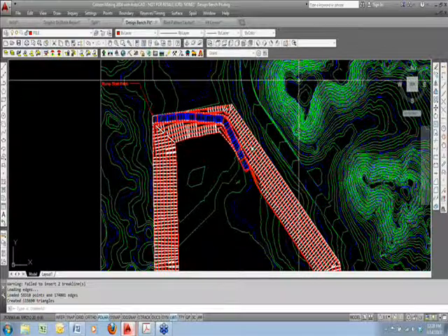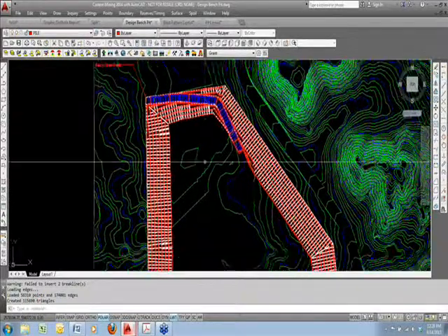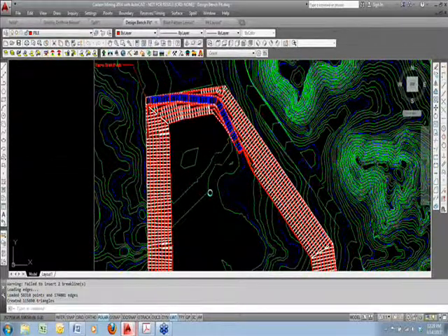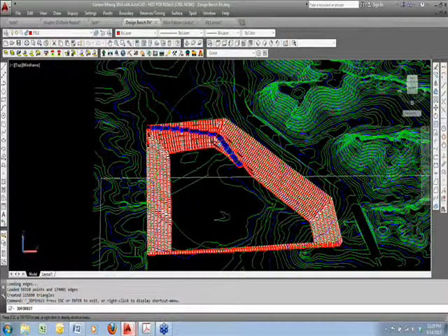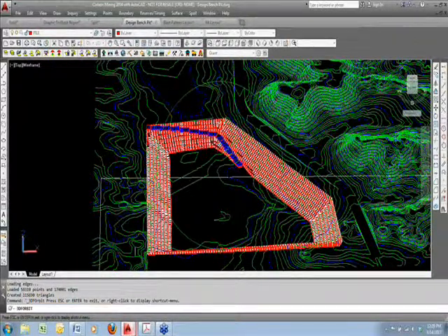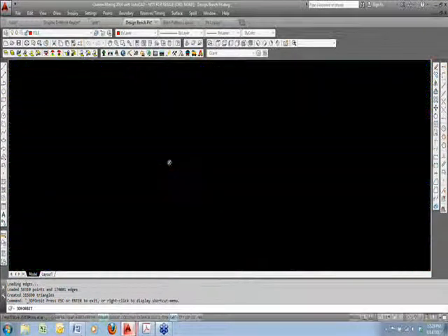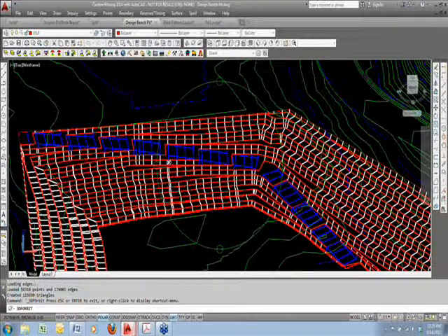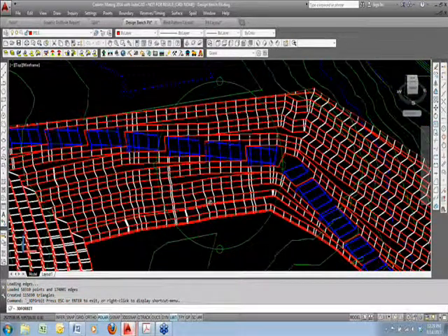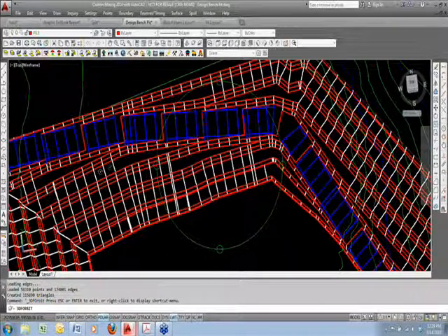But now let's take a look at this in 3D. We can do AutoCAD Orbit. And that taper that you saw, there was, I think, a 200 and a 400 distance. That's referring to this amount. It's a little easier to see when you're in plan view looking straight down. You can see how this bench has 50-foot width here, and then it begins to taper down to 0. You want to make sure these slopes all stay the same. You don't want to have your changing slope on your high wall, so it's very, very unique how it does it now.